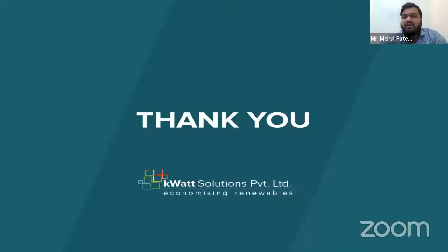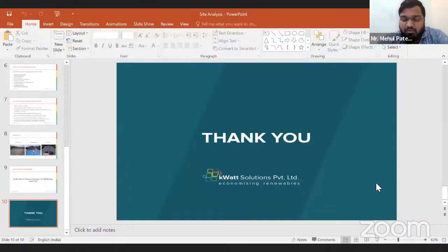Fine, so this was just a small thing. I hope you have got a fair idea of the ways to estimate the solar capacity of any client. One, again repeating, is electricity bill analysis. There were 5 parameters that we discussed which are required to see in the electricity bill to estimate the capacity. Second is using the area. I have given a small example of a 1 kilowatt system, which requires approximately 8 meters square area. Accordingly, you can do the scalability.